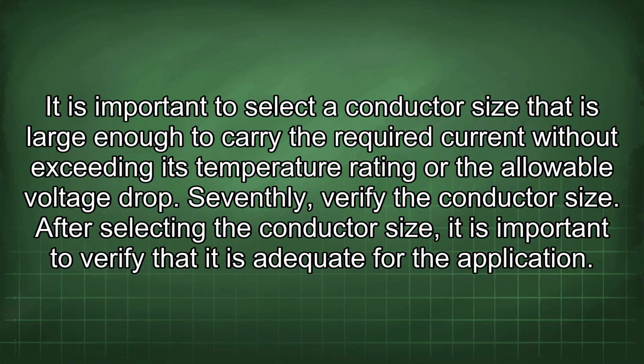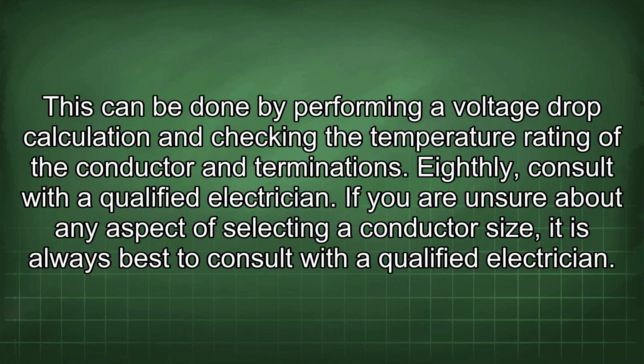Seventhly, verify the conductor size. After selecting the conductor size, it is important to verify that it is adequate for the application. This can be done by performing a voltage drop calculation and checking the temperature rating of the conductor and terminations.